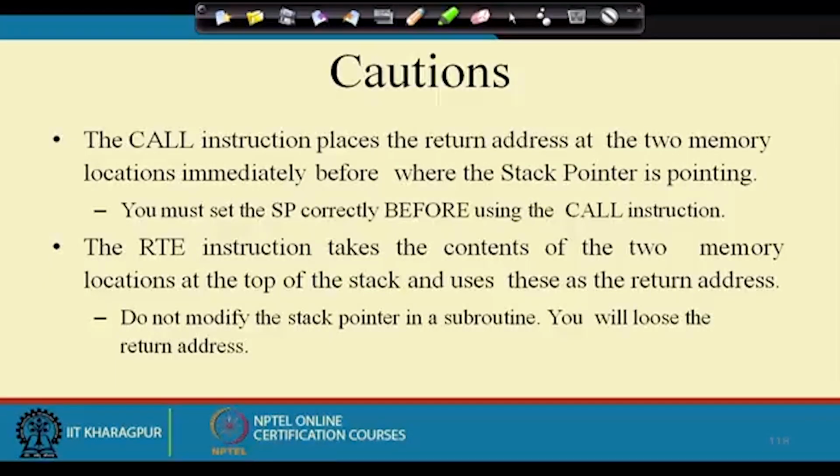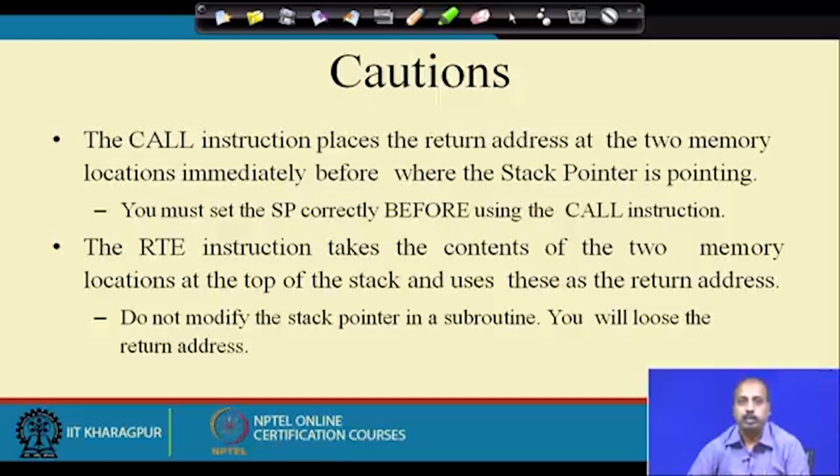On the other hand, the return instruction takes out the content of the 2 topmost memory locations. So, naturally, if you are not careful enough and modify the stack pointer register inside the subroutine, that may cause harm, because while returning from the subroutine, whatever the stack pointer value is, the processor will access the top 2 locations and put them onto the PC.